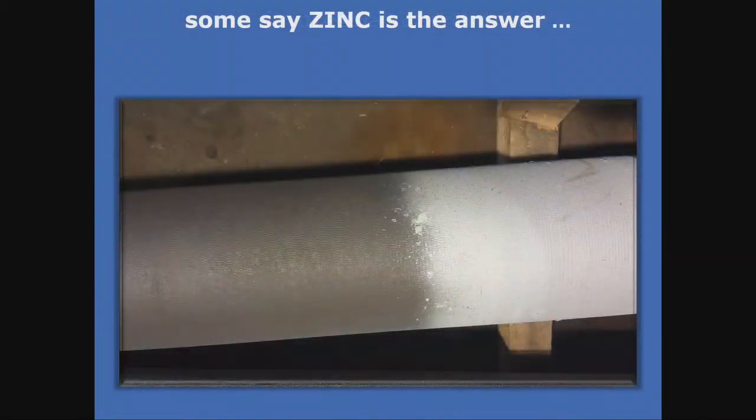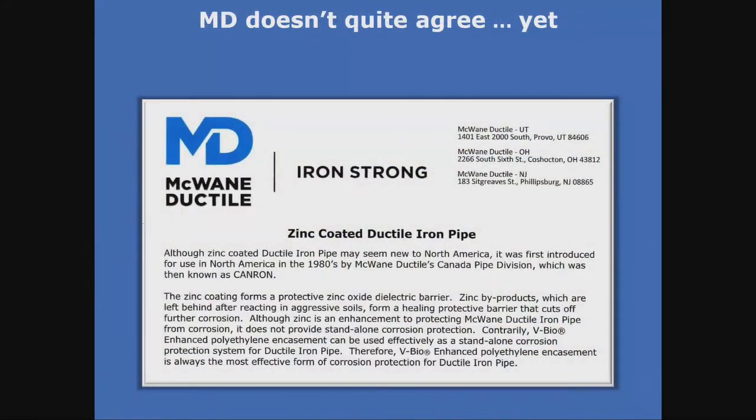Some say that zinc pipe is the answer. It's very popular in Europe. But zinc, as we know from that other chart that I showed you, is basically a sacrificial anode as well. So once the zinc is gone and eaten up on the pipe, then it'll start attacking the pipe. So it's a really good backup system. And this comes from McWane, and McWane and Canada Pipe are the same. McWane is the manufacturer. And basically what they say is that zinc is an enhancement to protecting ductile iron pipe from corrosion, but it is not standalone. We need something else to be added to that.